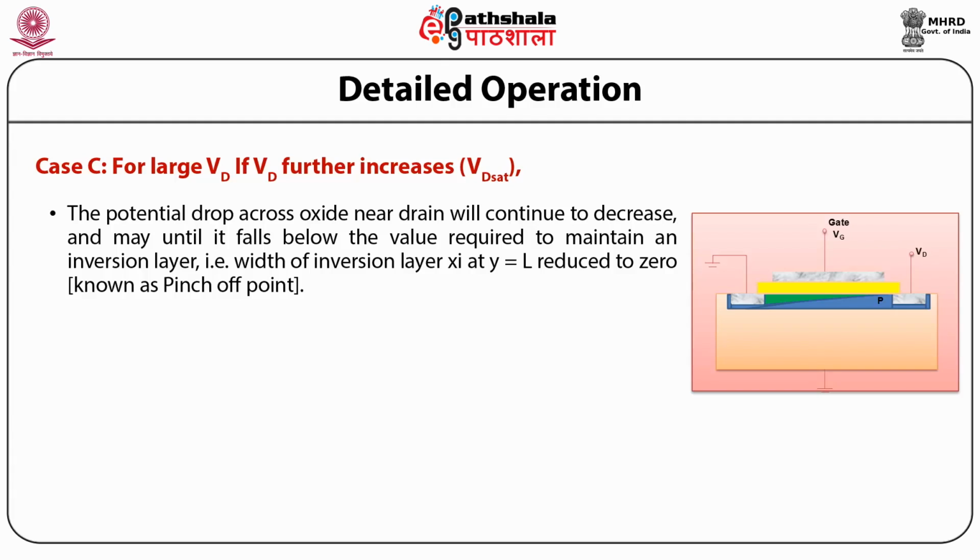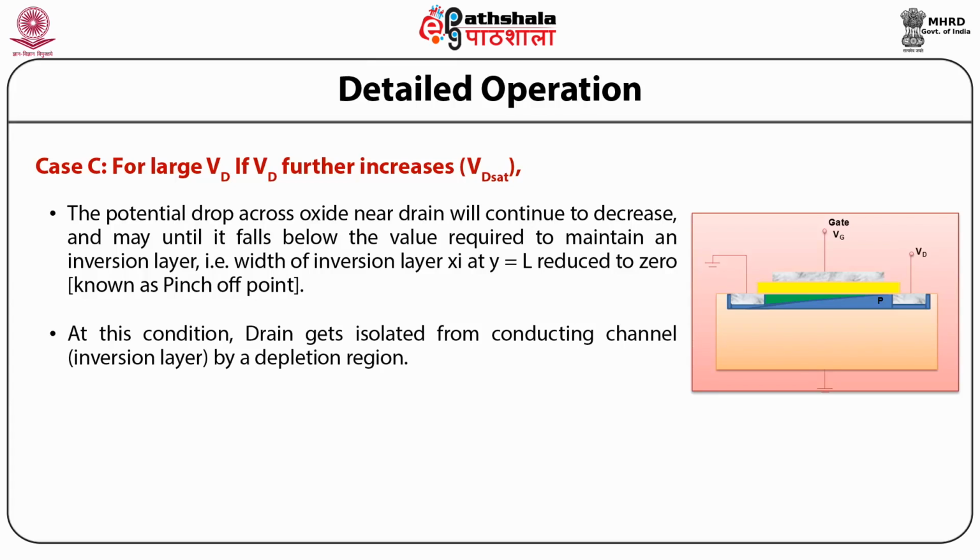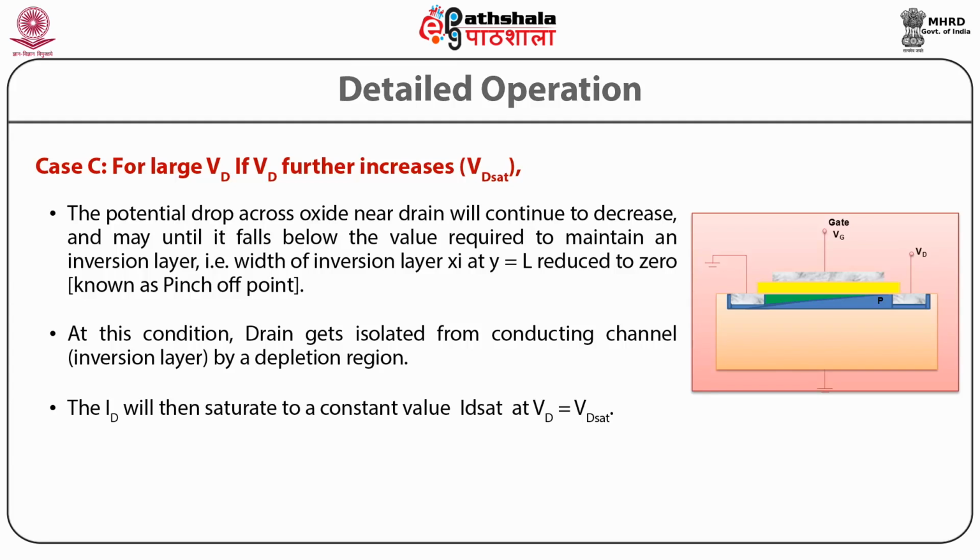This is known as the pinch off point, which is denoted by P in the right hand side figure. At this condition, the drain gets isolated from the conducting channel by a depletion region.